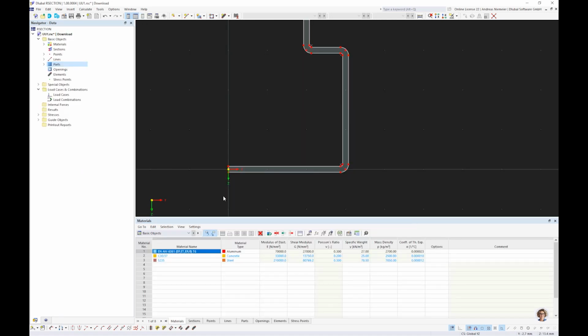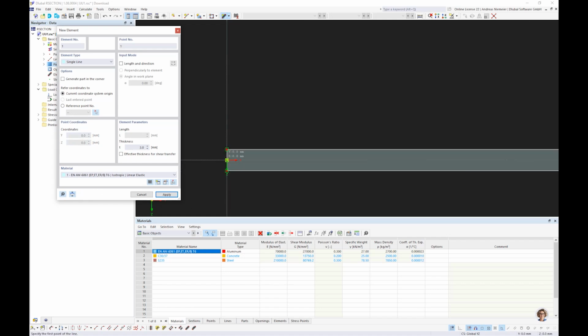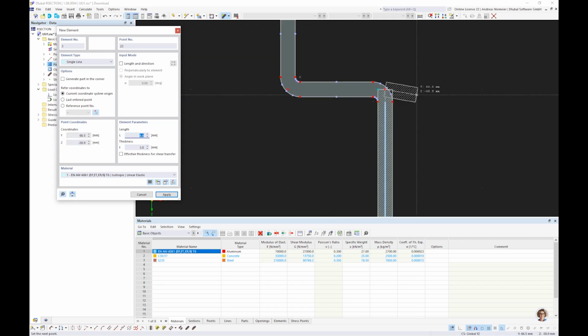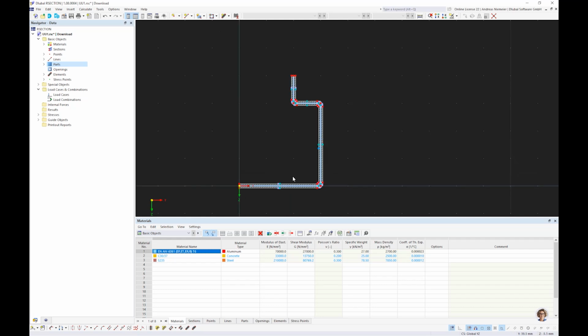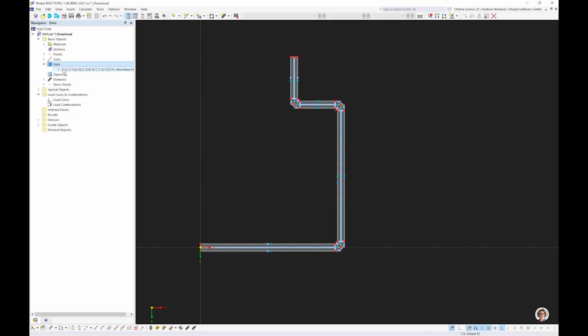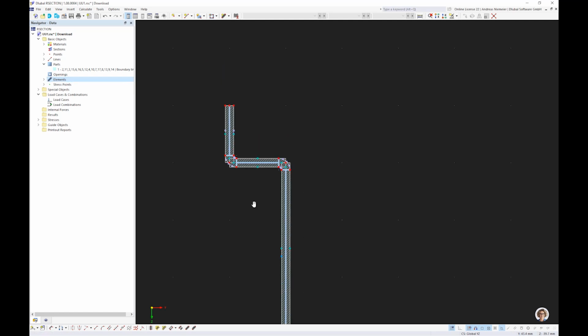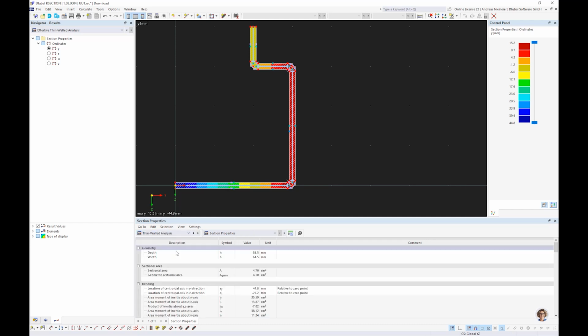And now let's insert these stripes. We can say we have here stripes with a thickness of 3 millimeters from this aluminum, and we insert it, and you see they are really rectangular and have here overstand, but this is no problem because we use for this mixed calculation of massive and thin-walled sections, for the bending relevant part, this part, and for the shear and buckling relevant parts, these stripes, and you see the program will move these stripes intelligently according to these roundings. So now when you calculate this, you get also section values, no problem, but then you can use it also for design, and this is the digital connection you can use efficiently.